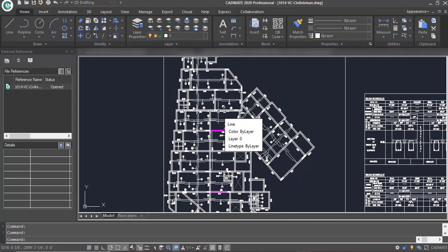A section is a cut or slice through a structure, usually taken in order to describe the interface between the structural elements. Elevations are the side view of the elements in the structure. They are often confused with sections because, just like sections, they are a cut through the structure showing the vertical plane. However, an elevation is at the very face of the element being viewed, and the purpose of an elevation is to illustrate the flow and interaction between the vertical and horizontal elements of the structure.